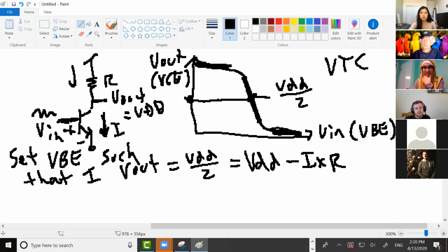Oh, okay. So let's see how you set a DC current through your amplifier. A slight pet peeve of mine is that this circuit, this current mirror circuit, is introduced as a current source, which it is, but the whole reason why we're introducing it right now is to set the current through your amplifier, so your V out will sit at the point that you want it to sit at. So we're just trying to set a default current through your amplifier.